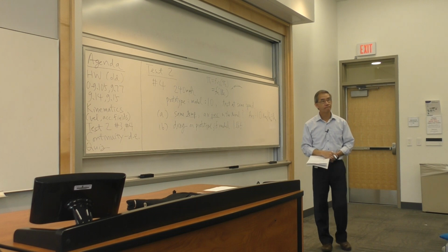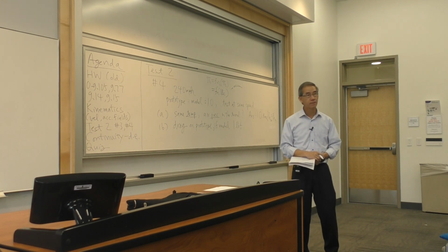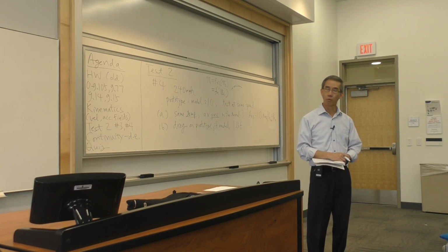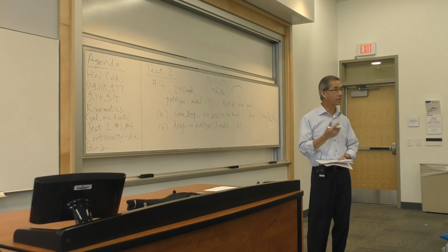Is the density constant for the prototype and the model? Is it the same? No, it's not. Think about it, ideal gas. Temperature the same, pressure 10 times. What is it doing to the density? And that change is what matches the Reynolds number.